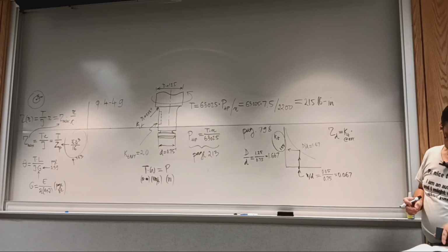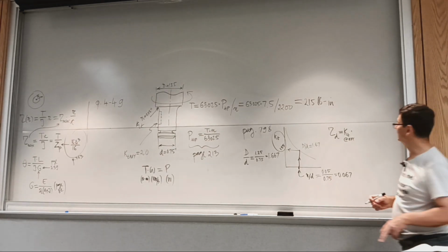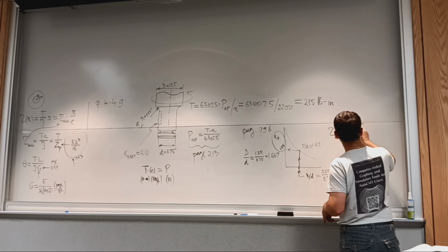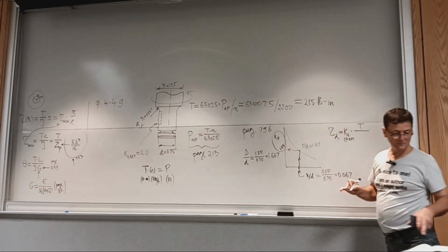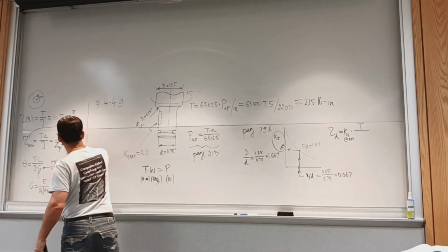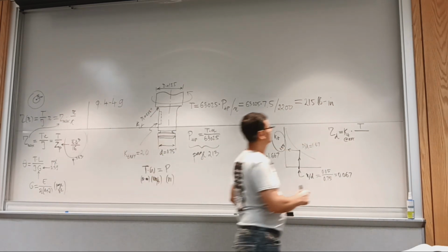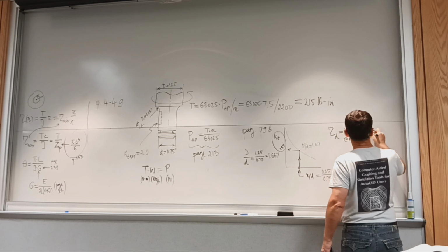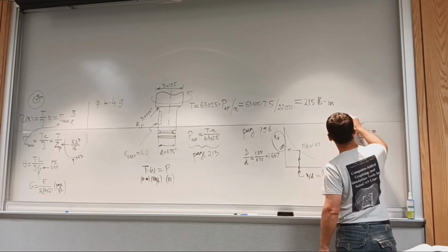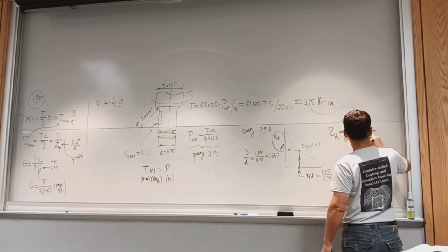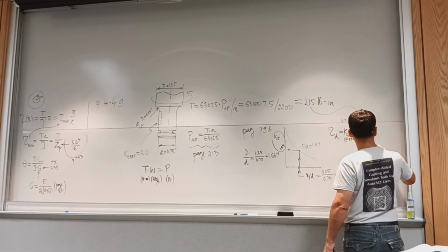T times pi, diameter power 3 over 16. We calculate with the minor diameter. So torque, we've got it, over, this is polar section modulus, pi diameter power 3 over 16, with the smaller diameter. So pi, minor diameter power 3 over 16. Okay, so Kt we said 2.0, torque, the one that we calculated, and then the diameter 0.75 inches.